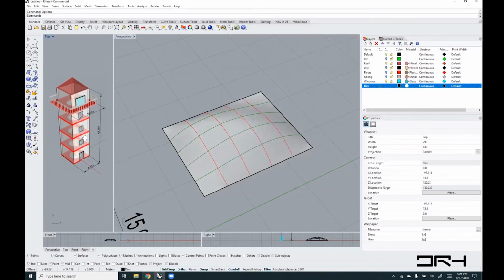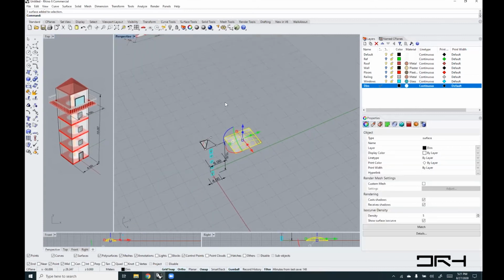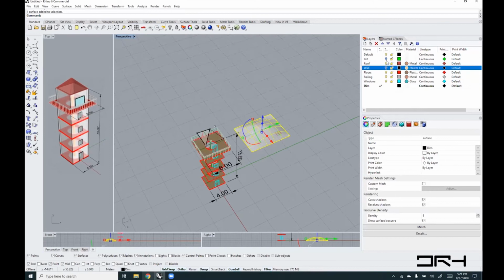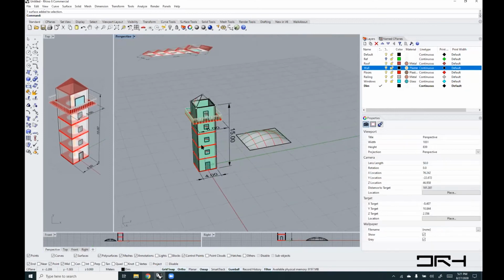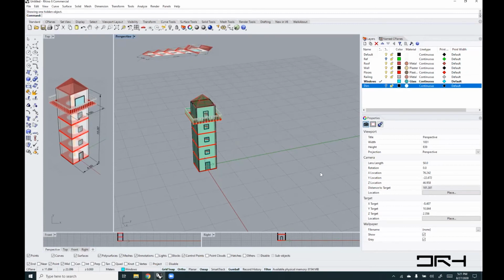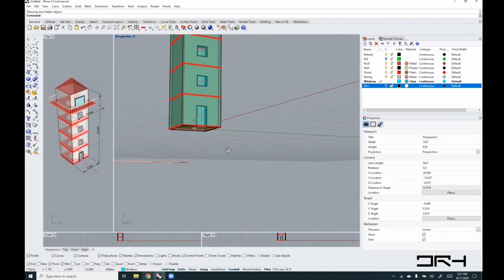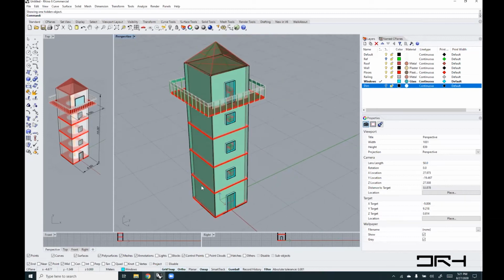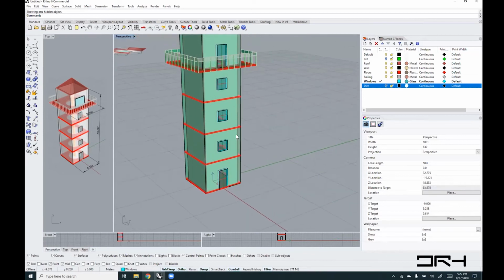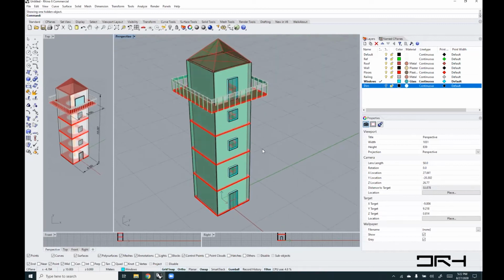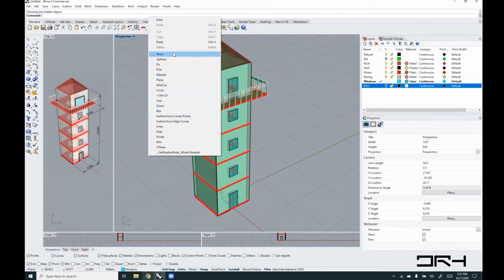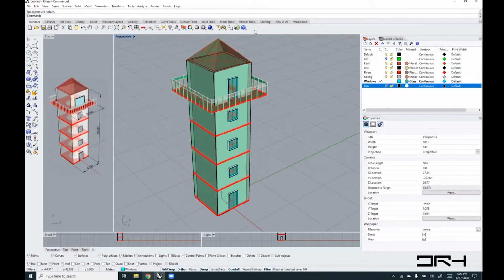And now you see how even with my tower, if I turn it on, where is my roof show? I'll turn off my dimensions. I started to see the back color of my surface, and it's dominating because it's looking through it and the transparency is very high. So you're starting to see things this way. And the back color is not transparent, so it messes things up somewhat. But yeah, you don't want to set the transparency to be super high.